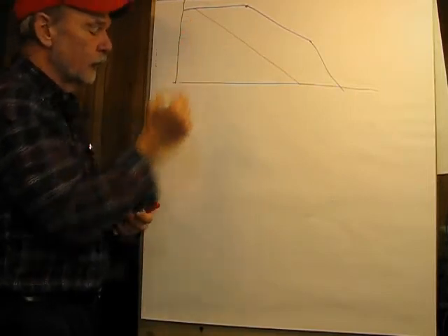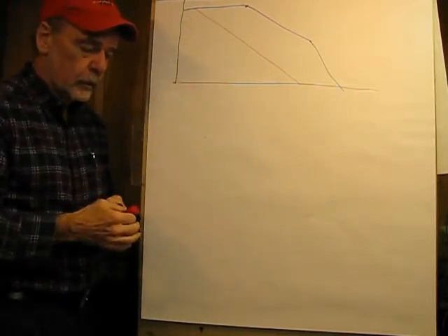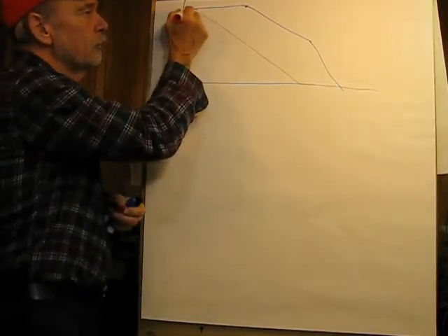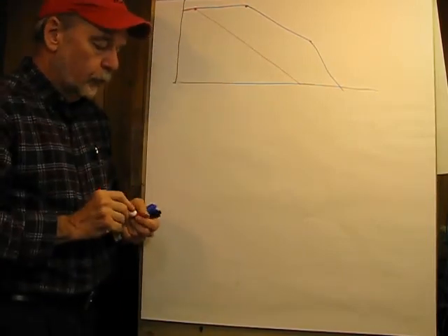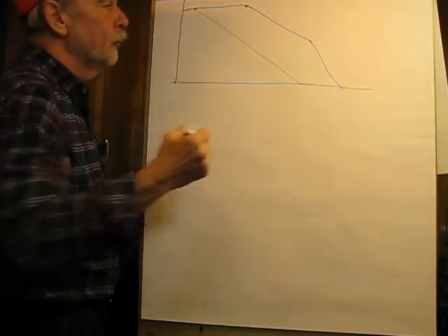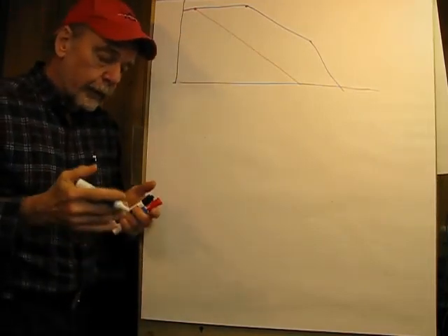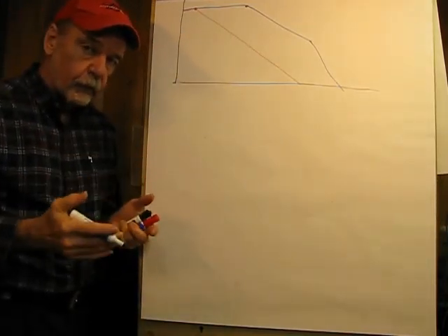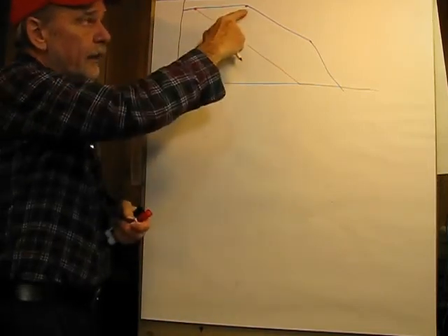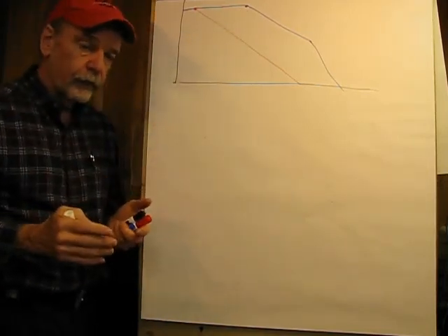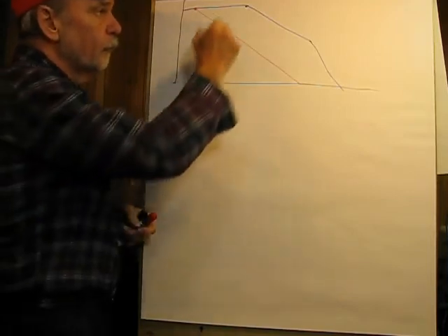It's not like this. And by dominant, I mean that there's only one critical frequency. So for the blue guy, we have one here, and do note that, thinking back to AC, when the absolute value of X sub C equals R is defining that point, and that's also going to produce a phase shift of 45 degrees. So let me write that down.